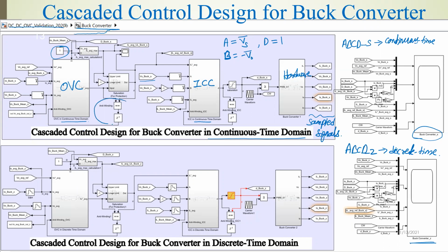This is our anti-windup. What it does is, if the output of the saturation block and the input of the saturation block are not the same, then it gives 0 to the integrator, so the input of the integrator is disabled, which we will also see in the next slide. This is a very important part, and this is what is used for protection.